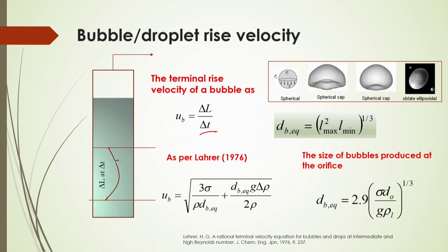because of which it will be moving higher. In that case, the residence time of the bubbles, that means how long it will reside in the column in the liquid medium, is called the residence time of the bubble. The residence time here will be lower, because of the higher buoyancy effect due to larger size bubbles.